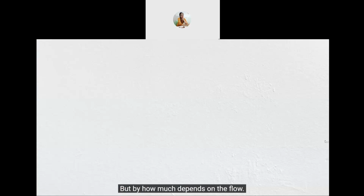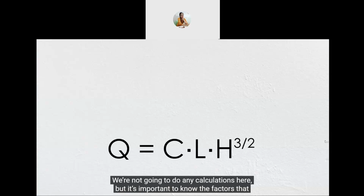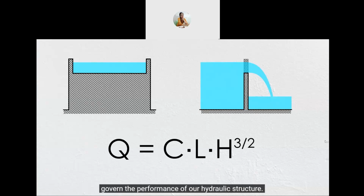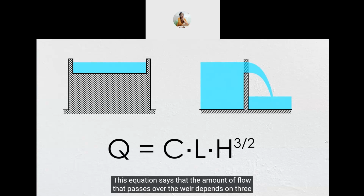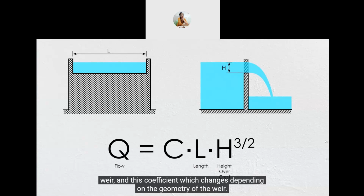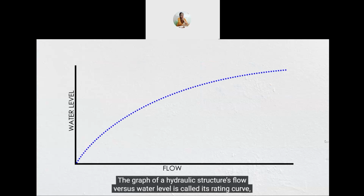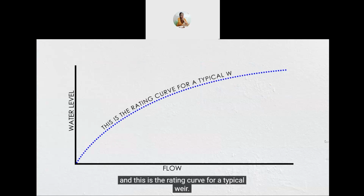This is the equation for flow over a weir. We're not going to do any calculations here, but it's important to know the factors that govern the performance of our hydraulic structure. This equation says that the amount of flow that passes over a weir depends on three factors: the length of the weir, the height of the water level above the crest of the weir, and this coefficient which changes depending on the geometry of the weir. The graph of a hydraulic structure's flow versus water level is called its rating curve, and this is the rating curve for a typical weir.